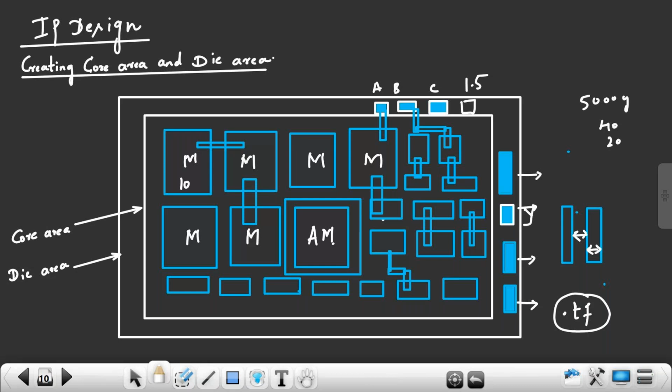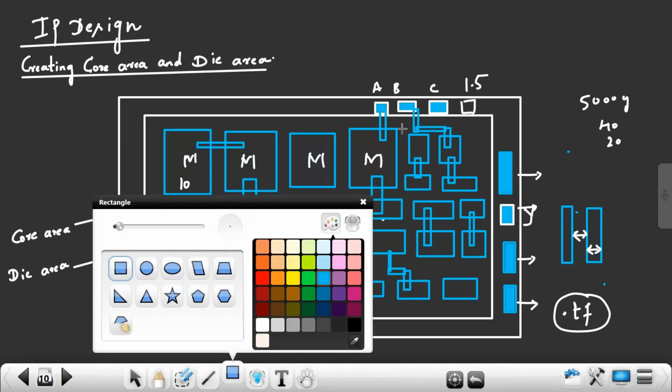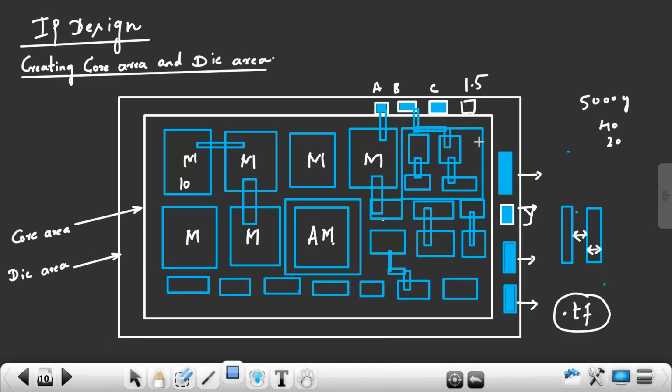So we have to do routing, placement, and building the CTS by following these rules given by the Foundry. If we don't follow, what happens? The Foundry cannot fabricate. That is called design for manufacturability. So I have to follow all the rules and regulations given by the Foundry, compulsory. The Foundry tells me that within a region, you have to maintain a minimum percentage of metal layers.